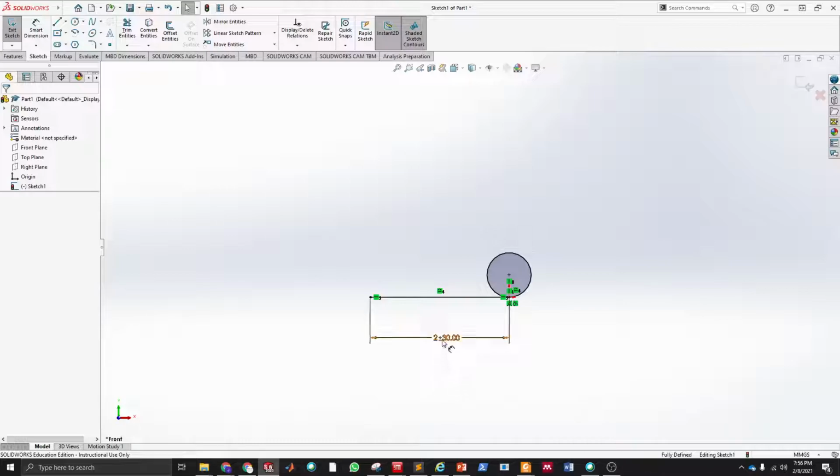So this is a way just to say, hey, what I accept as the error of this 30 millimeters long line is 2 millimeters. So this line can either be 32 millimeters or 28 or anything in between, and I will be fine with that. Of course, having tighter tolerances, more exact dimensions, is more expensive. And that's why some industries like Formula One, aerospace industries are so expensive, because they have higher tolerances.